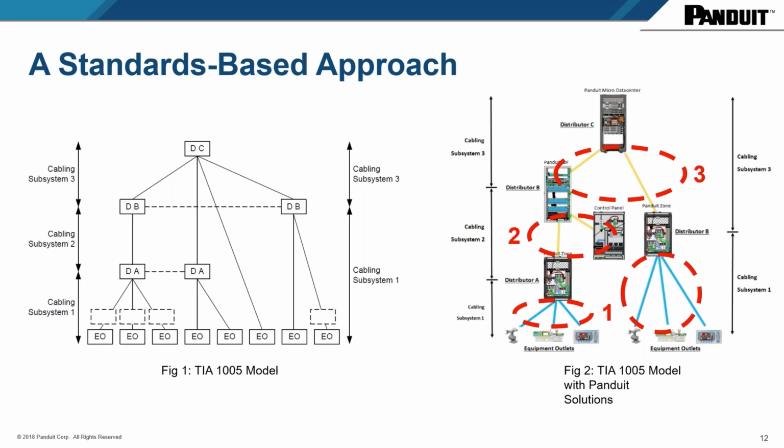Copper connectivity is sturdier, and there are a lot of connectivity solutions that you find selling in the industry that are copper connections. You will not find many companies delivering fiber connectivity to the edge devices. Generally, the connection between an edge device and a zone enclosure is under 100 meters. Therefore, you could use copper.